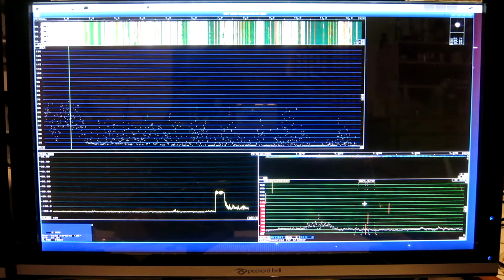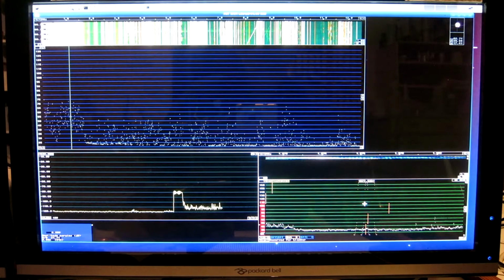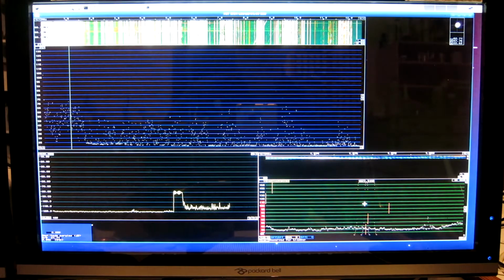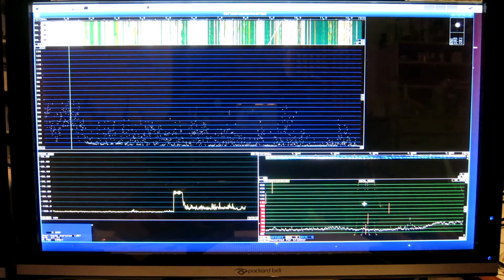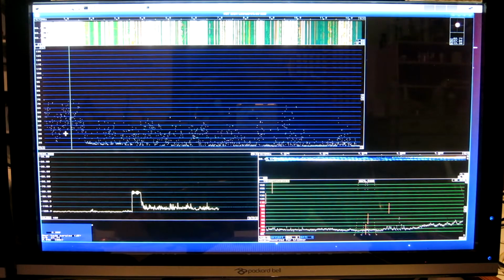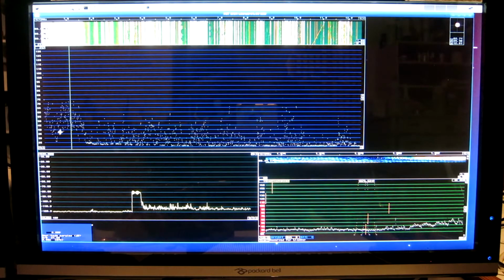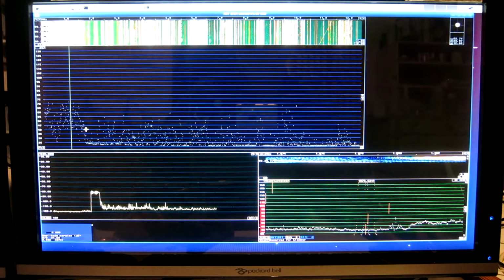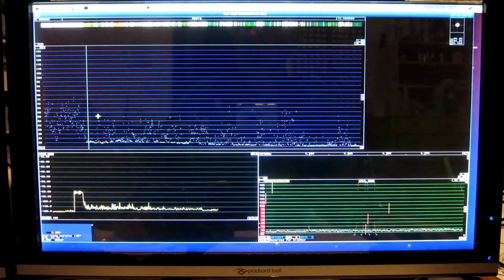There is no need for more gain. If I continue to tune, trying to find a low level, the noise floor is about 5 to 10 dB above the noise floor of the card. So for optimum reception, I need an amplifier with near zero gain from DC up to, let's say, up to 1.5 megahertz or so.